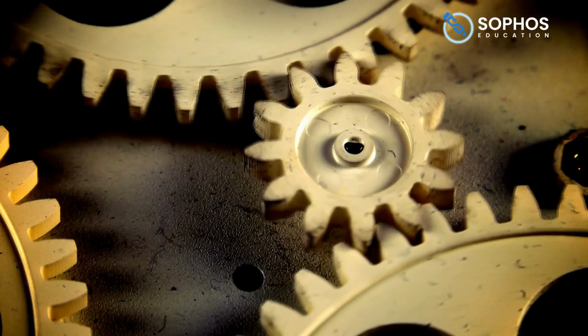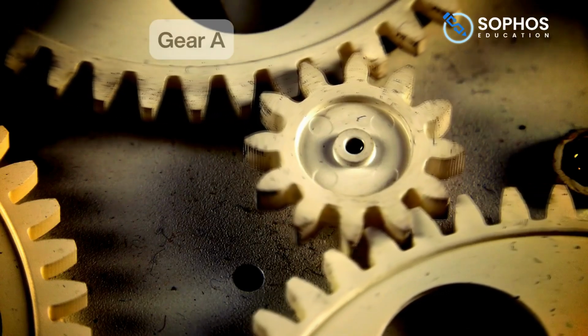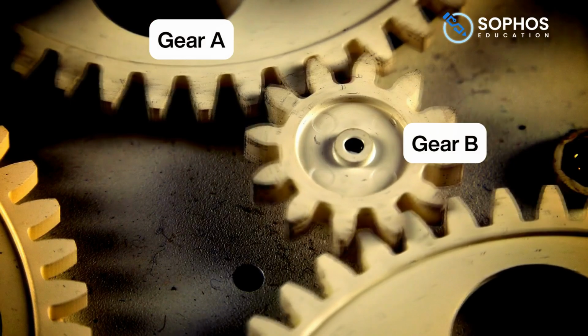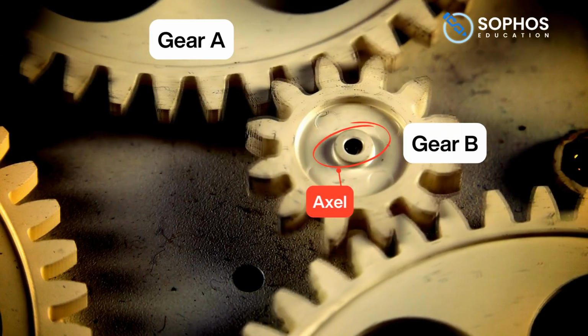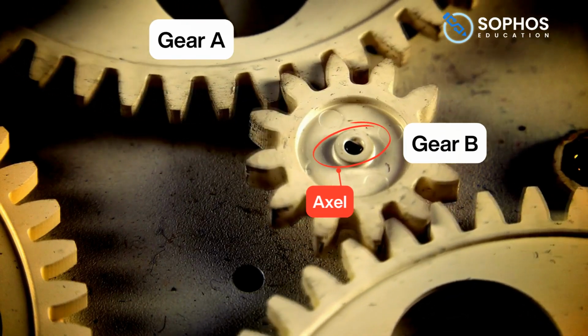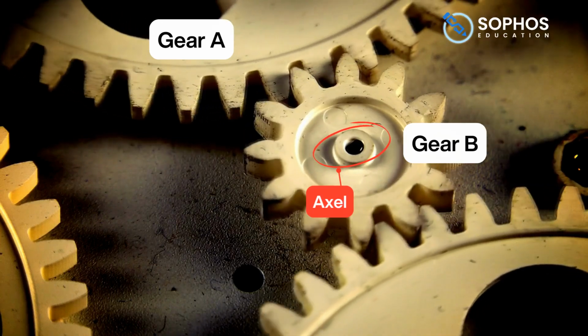Now let's look at how gears work. Consider a simple gear system with two gears, a large gear, gear A, and a smaller gear, gear B. These gears are mounted on axles that serve as pivots. When gear A rotates, its teeth push against the teeth of gear B, causing gear B to rotate. Because of the meshing teeth, both gears rotate in opposite directions.